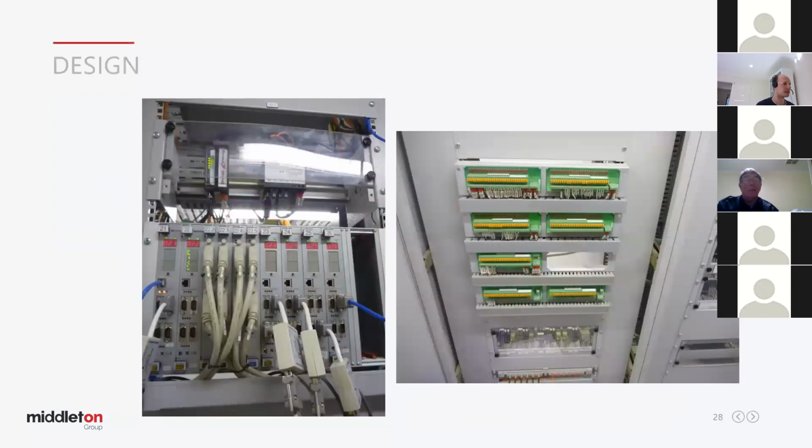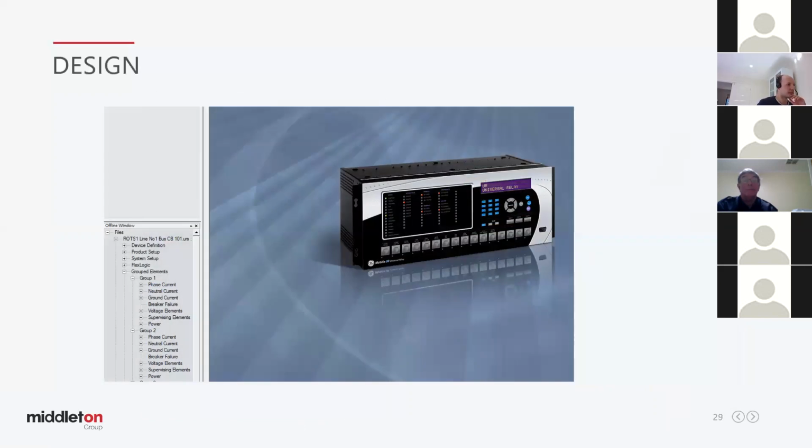Excellent. Let's move on. Okay, SCADA, digital interface cubicle for engineering access. We've got ports available. We'll connect up those ports, update those drawings, make sure everything's okay, assign some IP addresses. We can then do our mapping table, which is really mapping out all the individual control and monitoring points and status points within the relay to SCADA. So we've got all of those addressed, indexed, and ready for the SCADA system.